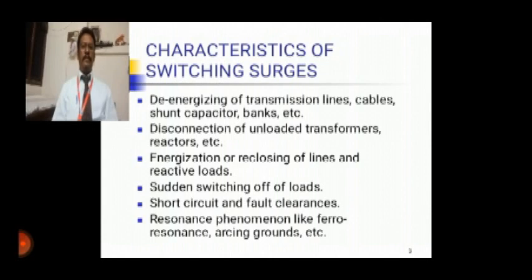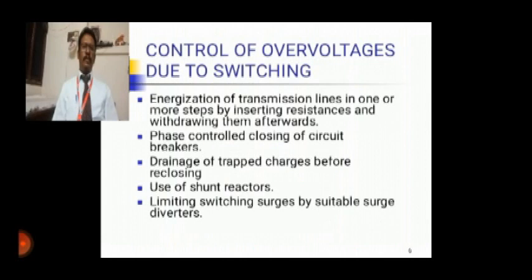Whenever a fault has been cleared, immediately after the clearance there is a possibility of switching surges, so we have to be more cautious at the time of clearing faults. Then resonance phenomena like ferroresonance, arcing grounds, etc. These are the important key characteristics of switching surges, which we have to keep in mind at the time of analyzing them. Next, control of over voltage due to switching.